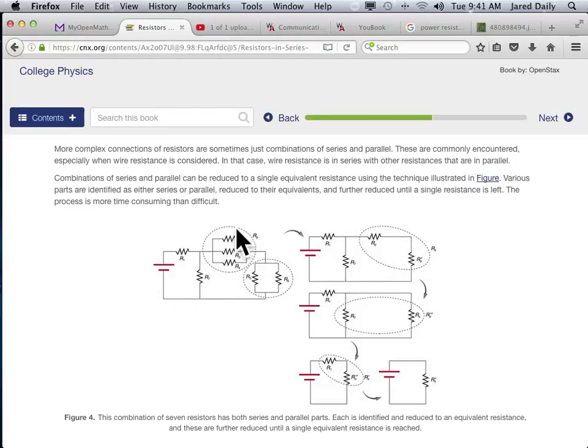So this circuit diagram, as long as you do the math right to get the equivalent resistance, is equivalent to this diagram. In other words, these circuits will behave the same. The only difference is that in the middle of this circuit, the current is going to split 3 ways and then recombine, and split 2 ways and then recombine. And in this one, it wouldn't. But it would still behave the same as far as overall resistance is concerned, and current and everything else.